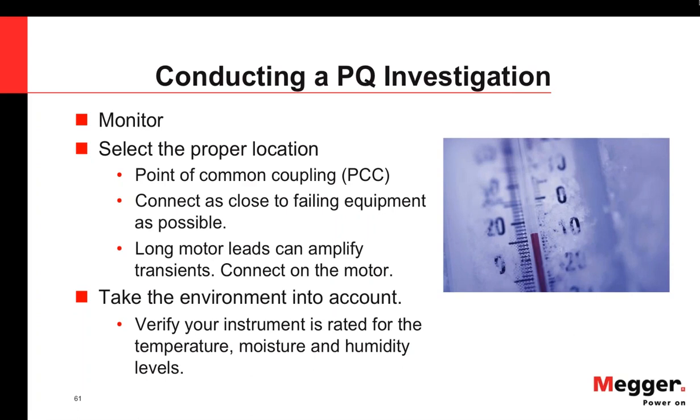Now, you can hook up a monitor and do some immediate checks right on the spot. You can look at your harmonics, your unbalance, and instantaneous flicker. You can also look at interharmonics and things like that, which I actually didn't cover. That would be in another session. If you don't find the problem right away, you may need to do some monitoring.